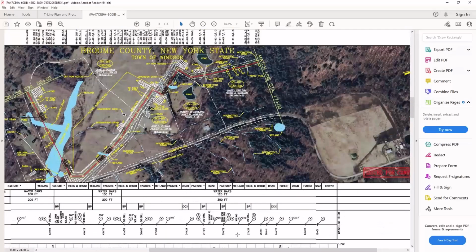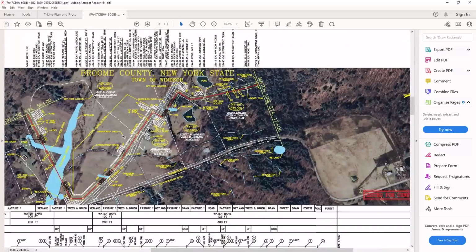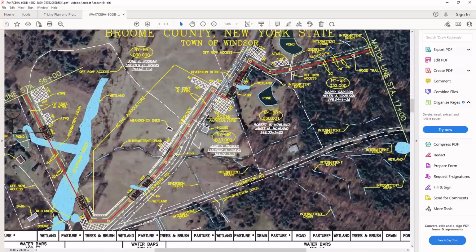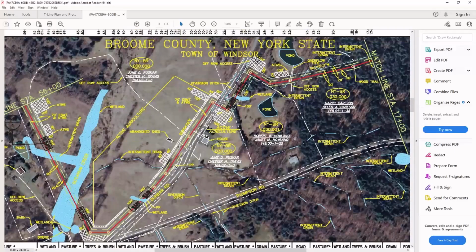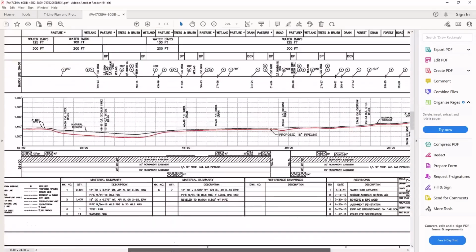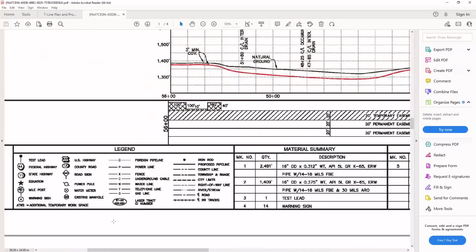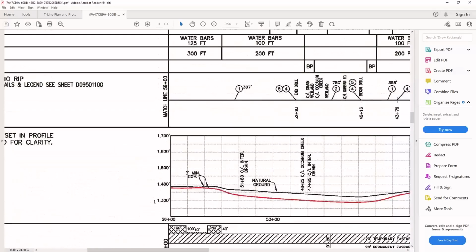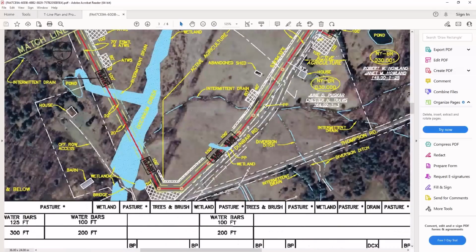This is going to typically have a satellite view of the pipeline's path. It can incorporate other little details, such as the appurtenance locations. And one thing that's useful is if you look down at the legends, they will often note other entities that are known in their corridor. So here we can see in the legend, this power line is a part of their alignment drawing, and we can scroll up to see that little P with the dashed line associated with it. This shows us our general alignment for our pipeline and our power line.